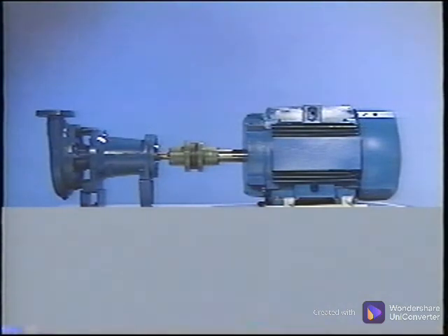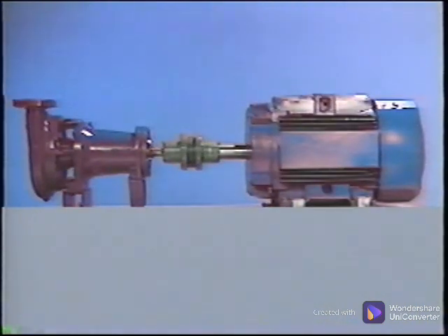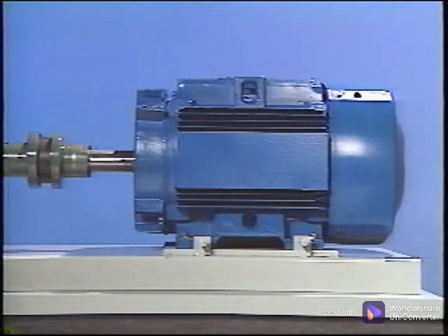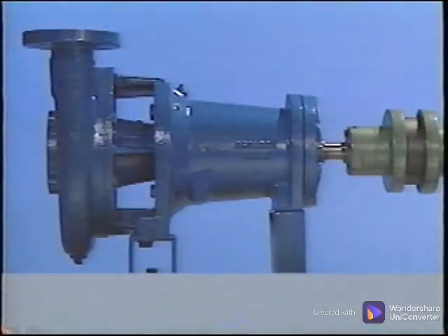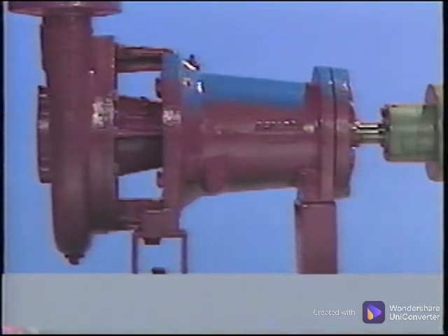Most machinery operates well above ambient temperatures, and the actual size of the machine will increase as the temperature increases. This would not be a problem if the machine grew the same throughout, but that is seldom the case. Instead, the fan end of the motor will typically be cooler than the coupling end and therefore not grow as much. If the driven unit is a pump and it is transferring a hot solution, it could grow more than the motor, increasing the misalignment.